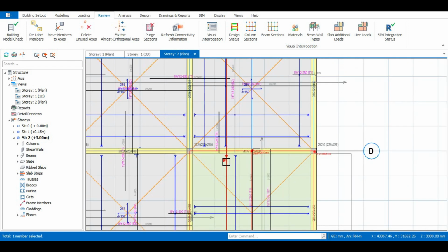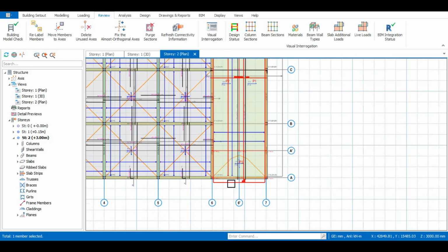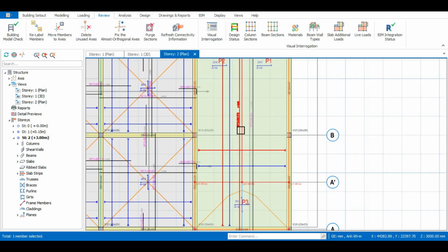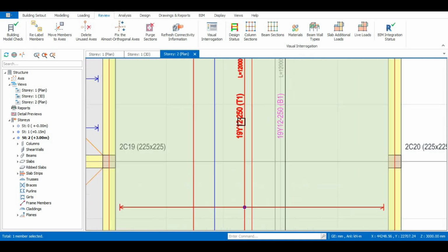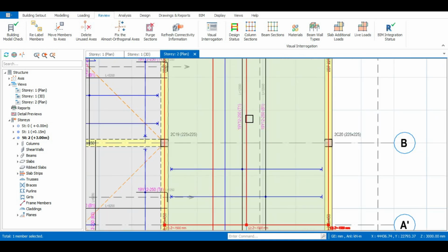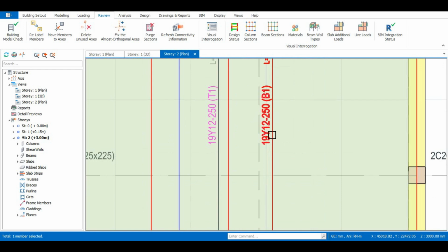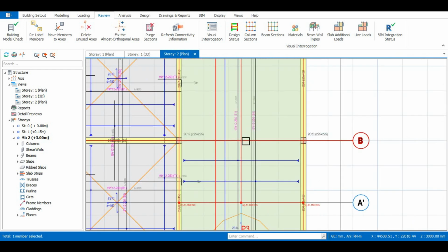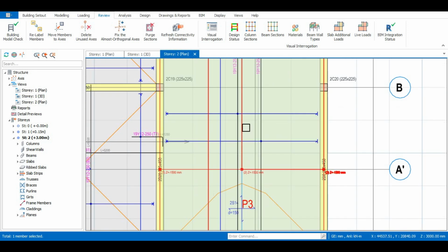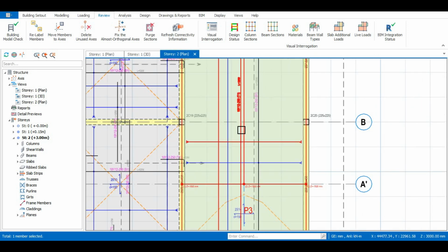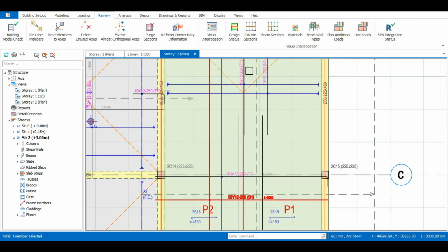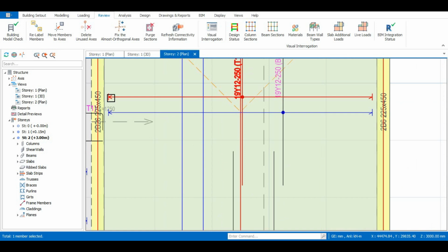And the second bar, the bar for the shorter span: you have 19 Y12 at the bottom and 19 Y12 at the top. What this also means is, when you click on it, let's go and look for where it is. So it's here, you can see it here now. The bar is spanning from here to here, but it's going to be arranged straight.